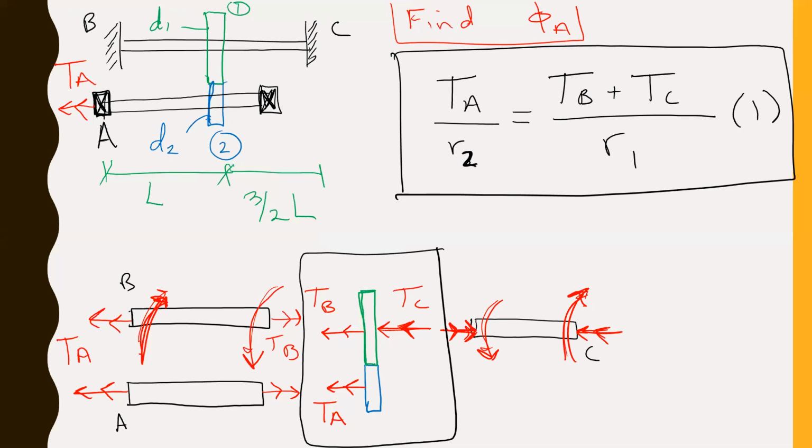There are some stopping points. In particular, B and C are fixed. So what can we gather from that? Torque should be equal for both parts of the rod. I don't want to say torque because we're talking about displacements here, but you're on the right track. Twist. The twist has to be equal. Or more, maybe same thing, but said differently, is that the sum of the twists has to equal 0.